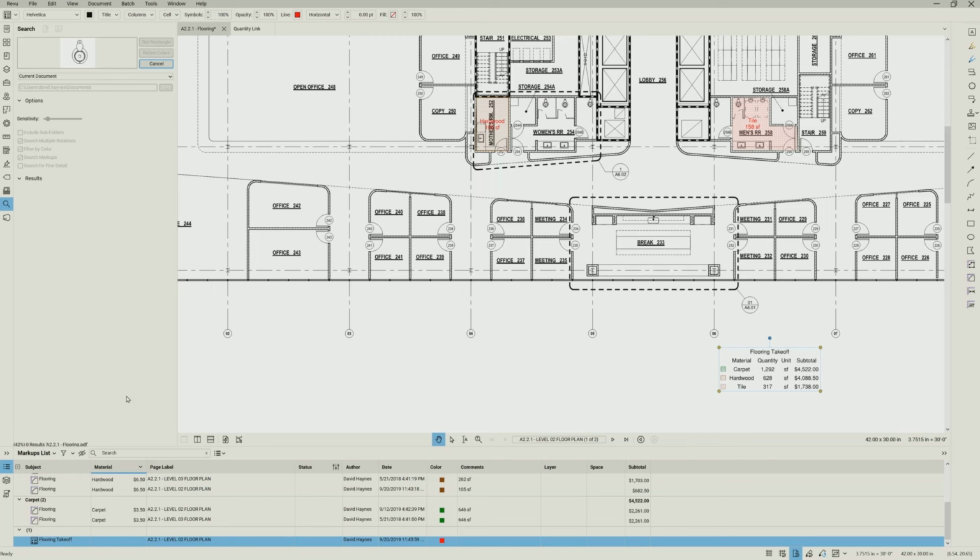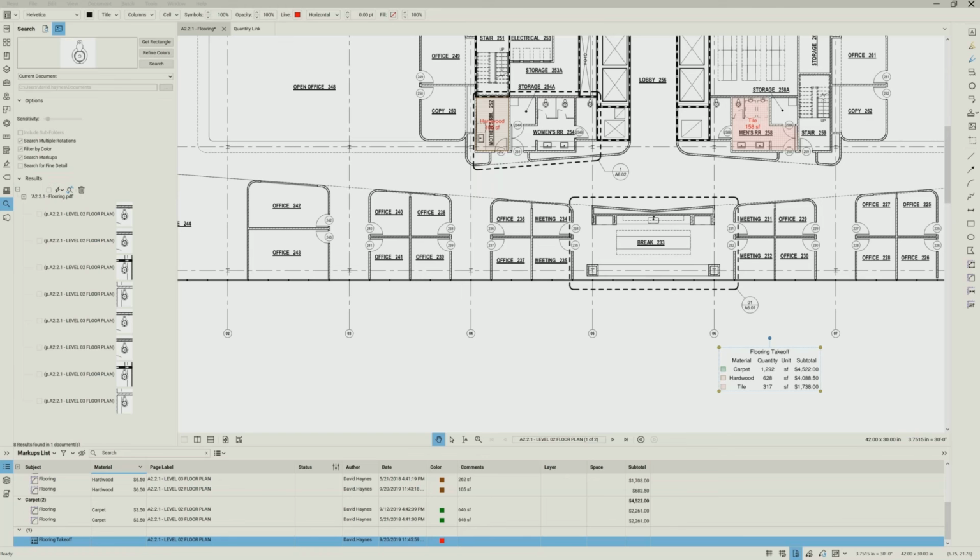And then from there, like what David had shown you, you can make a table like he did, so that you can summarize that count. You can see right there, David did a visual search and can apply a count measurement to that. Some of that happens through the sensitivity and these options, so I can further modify it. And the more sensitive you go, the longer it's going to take. The more sheets you have and the more items you have, all those are factors. Yep, exactly. There are also some other options here, but that doesn't get into our QTL. So visual search is very powerful, but like with everything that's powerful, there's some danger, I guess is the best word. We all like danger.